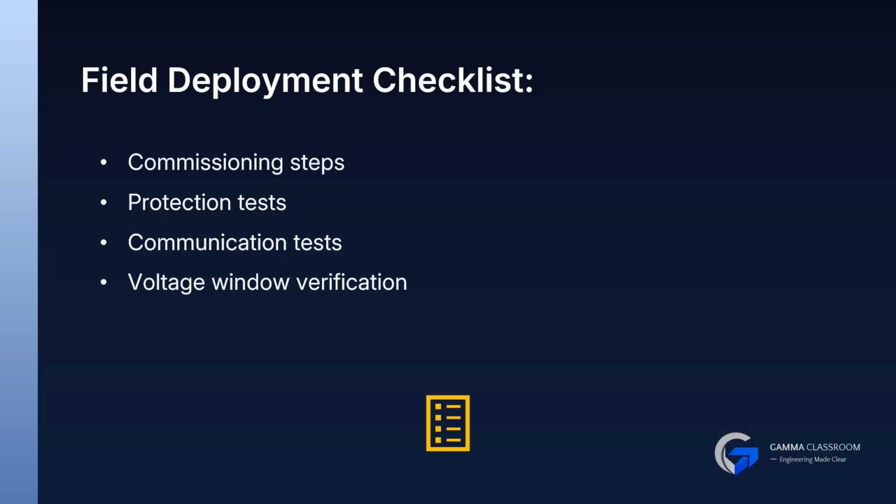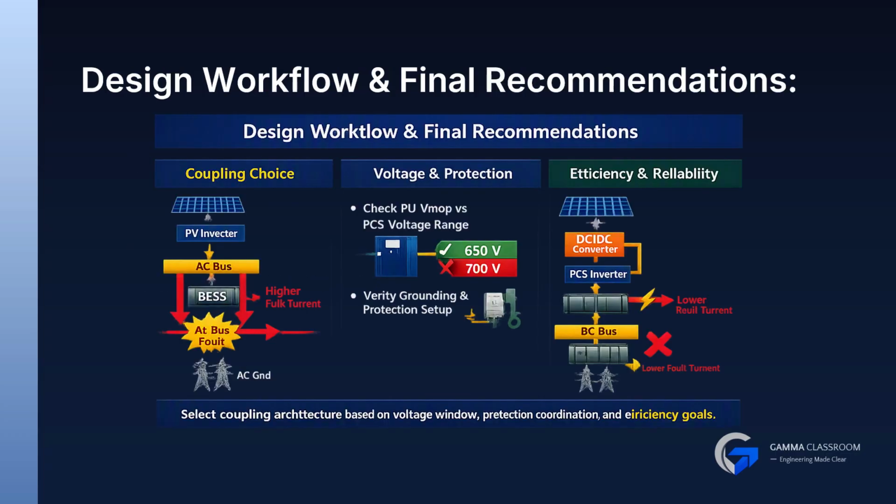A thorough checklist ensures safe and compliant operation from day one. When selecting a coupling architecture, always start with voltage window alignment, confirm protection coordination, and aim for the highest efficiency within inverter limits.